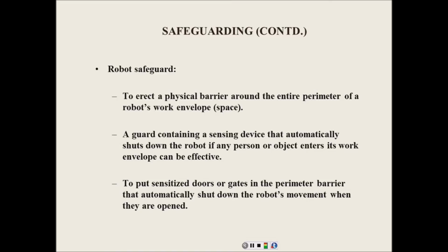The problem with the KUKA is you're going to have to use high-speed teach, because if you use regular teach and put it to 30%, it's not 30% below 250. It's going to be 30% of 250, which is the robot moves really slow. So on the KUKA, we'll be over there 5 minutes watching it run as just a standard program. So on the KUKA, to get your speeds like everybody else has, you will have to set it to high-speed teach, but honor the speeds that I tell you to run it at.